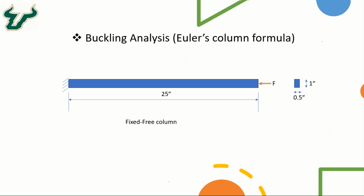And so with this, now let's take a look at the buckling analysis by using Euler's column formula. We will be using the same geometry as we used for the calculation of fundamental frequencies for this column, which is fixed at one end and the other end is free. Now in the buckling analysis, we want to see what is the critical buckling load that will cause this column to buckle when the load is applied in the axial direction in a compressive manner.